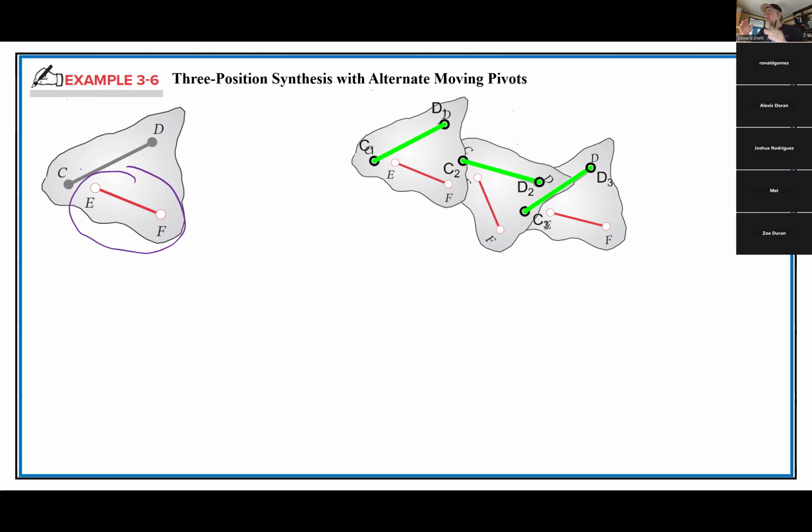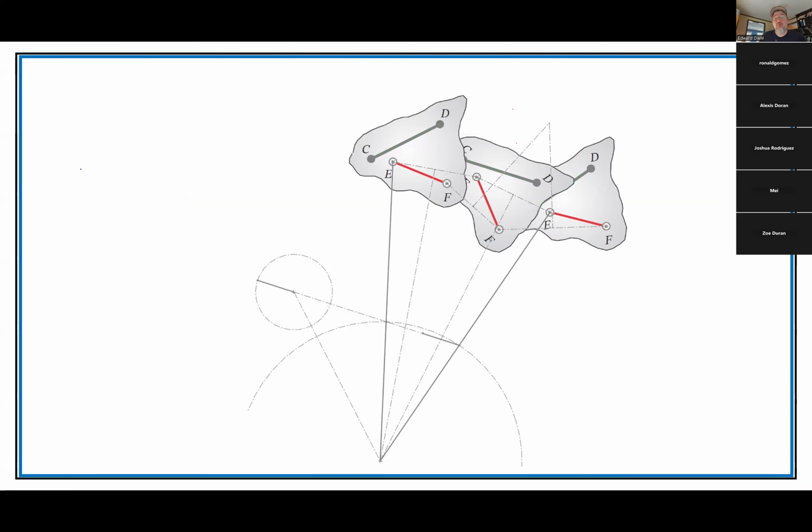So you could kind of see, oh, the attachment points weren't great. Maybe that's what we just found out. Let's try other attachment points, E and F. So if you picked these two spots, we've definitely moved, but we didn't really change the general shape of this thing. We still needed to have the rocker up high and, let's call it, the crank down below. It's not really just another rocker. But we were able to shift it from them being in line, right? So that's the little tweak that we made.